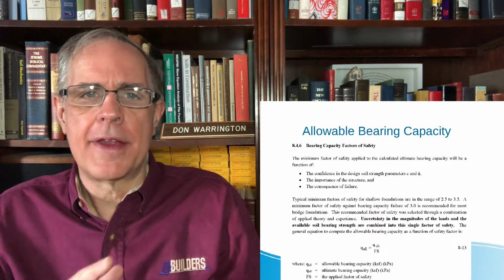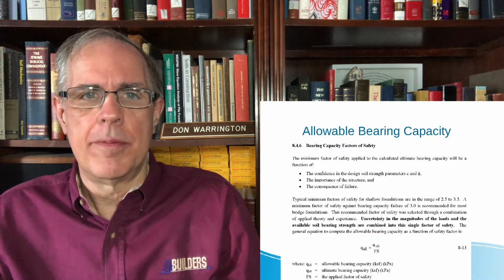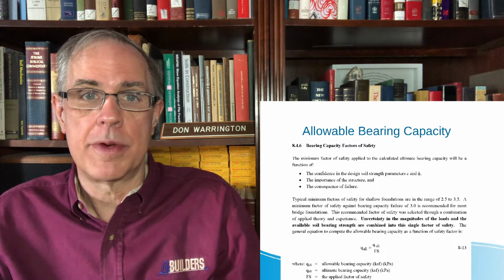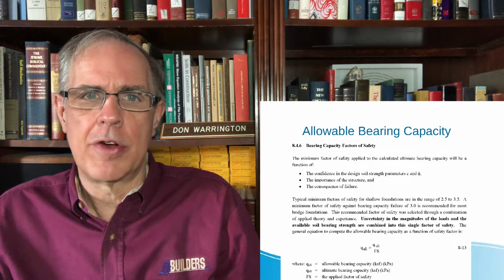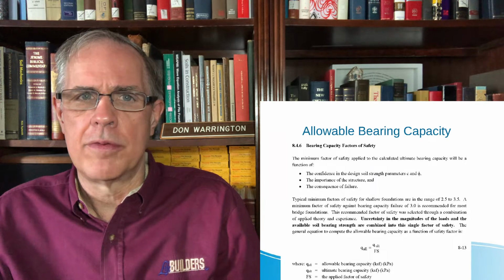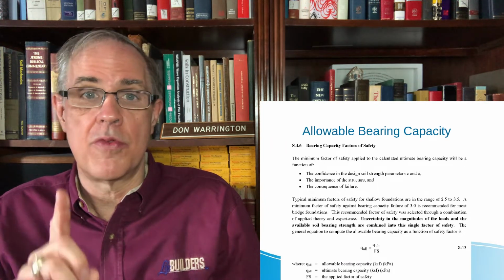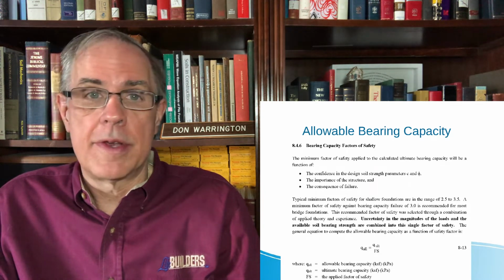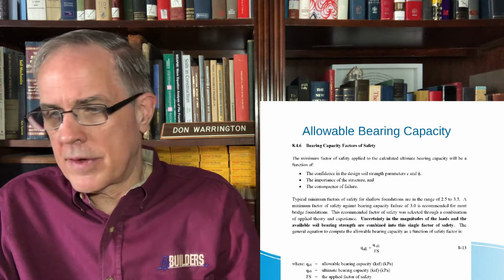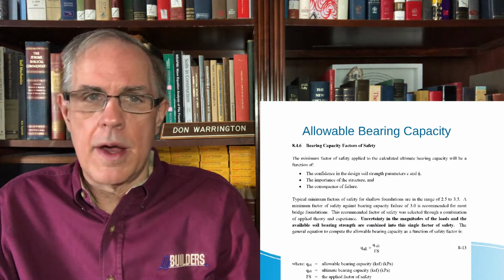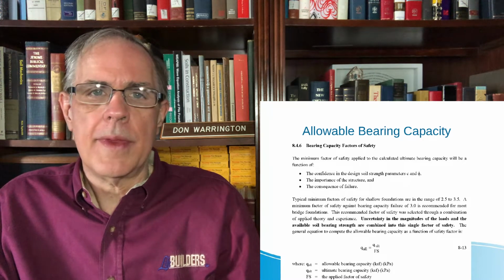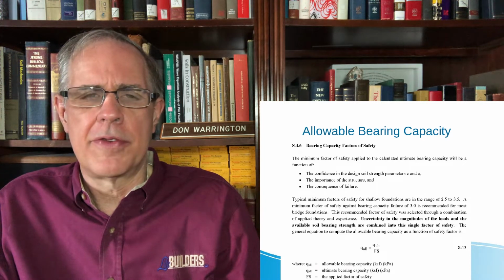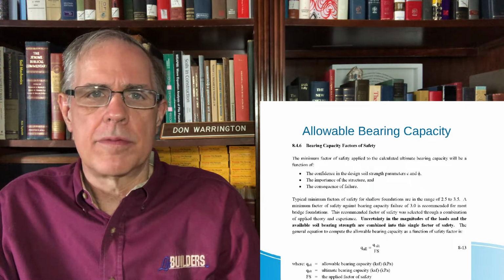Obviously, probably the highest factor of safety, if you could get it, would be a lower bound type solution. And in fact, there are situations where a lower bound type solution would be appropriate. They're not very often. The problem is that lower bound solutions have not been developed very well for shallow foundations. Other than the one that I showed you, they're not common. And they have their limitations. So normally, that type of factor of safety is reasonable. And that's why we have factors of safety in this particular field.